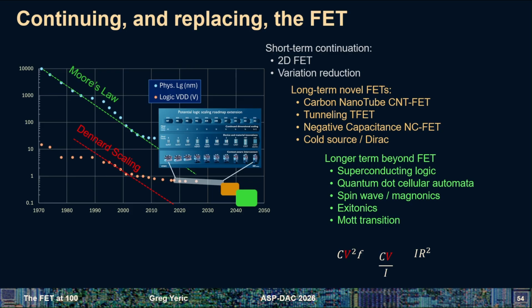There are Mott devices. Vanadium oxide is a Mott material, and there are Mott transition devices made out of vanadium oxide. The problem with vanadium oxide is it has a phase transition, meaning that it'll change the structure, like the grain structure.